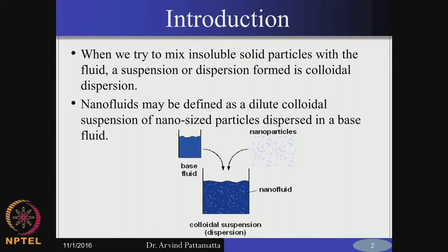One of the important challenges in synthesizing nanofluid is how do you maintain stable suspensions of these nanoparticles, because nanoparticles usually have a higher density than the base fluid, as they could be metallic particles or some oxides. Gravity is acting on all these nanoparticles. If you do not do any special treatment and you simply add them, stir them, and then wait for a few minutes, you will see immediately all the particles getting sedimented, and there is no suspension actually formed.